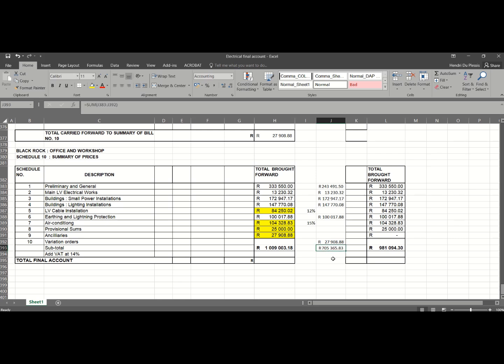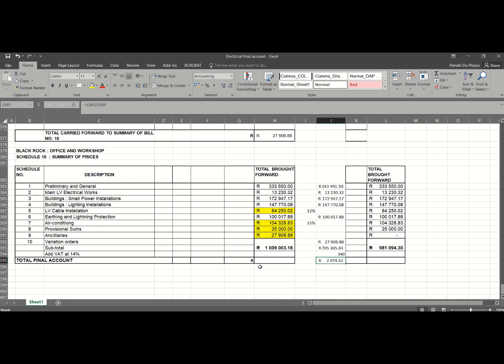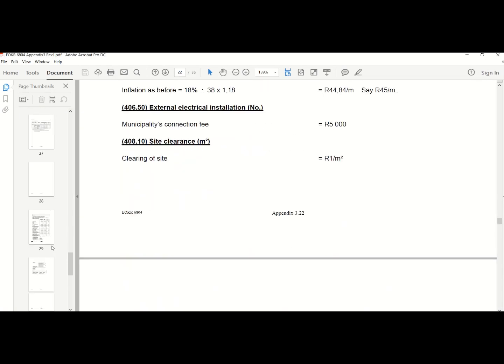Okay, and so we get to our new rate, and for this building it was more or less 117, and it's two buildings of 70, or 70 times 2, so we had a construction rate of 2,000 Rand per square meter. So if you have your elemental estimate, what would happen is you would take this rate to use in your elemental estimate.